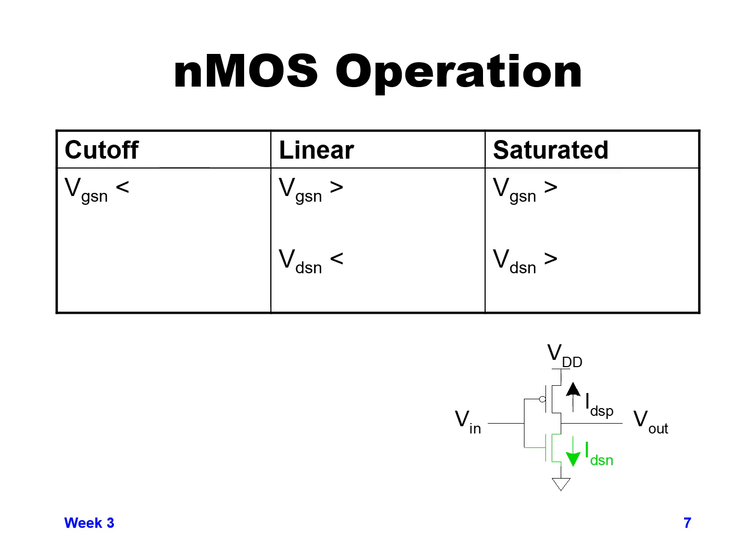So let's go through more detail of the 3 regions of operation for an NMOS transistor. You can see in the lower right-hand corner, if we have Vin, the NMOS transistor is the one highlighted in green. The first region of operation is cutoff, when the transistor isn't on. The value of VGS for the NMOS has to be less than the threshold voltage for the NMOS. If it is, then the NMOS does not conduct any current and the NMOS is off.